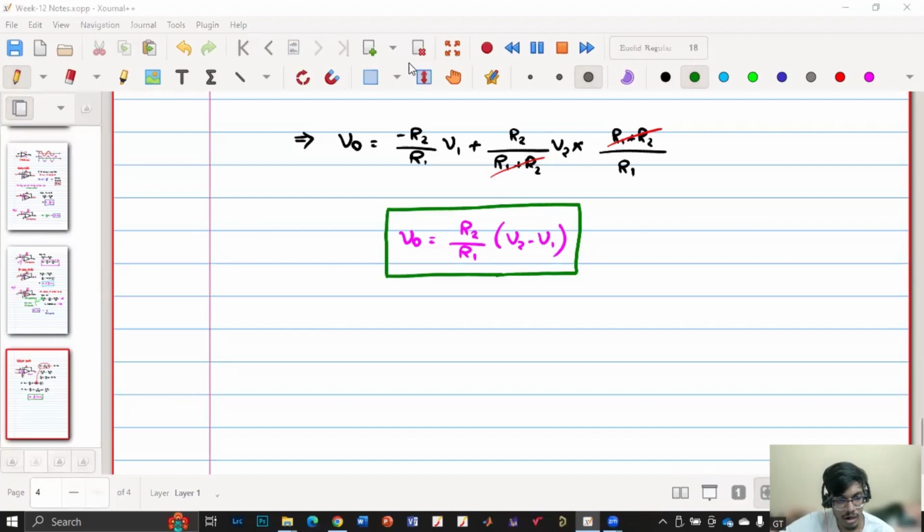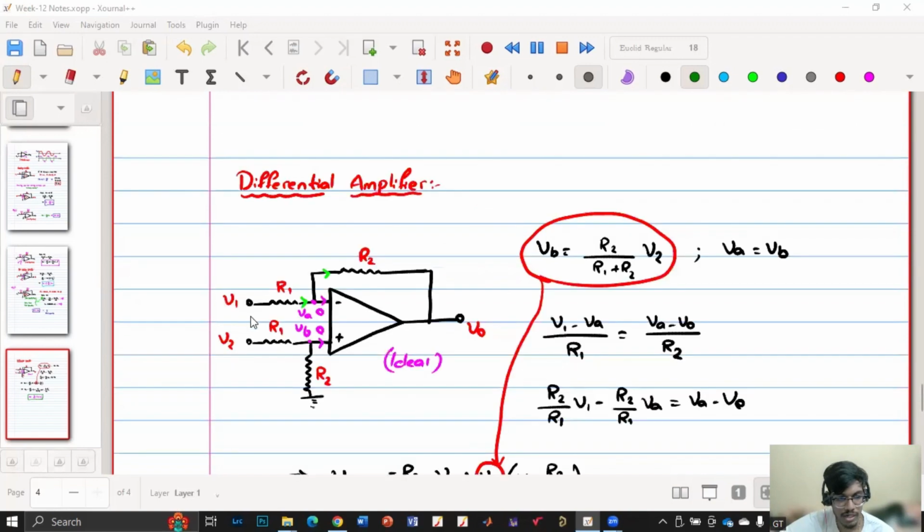So 101 ohm, yeah, that can also be considered, but usually this resistor should be a little bit high, else there will be a loading effect. So this resistor should be like in the data sheet they'll give. It would be better if they're at least in kilo ohms, so at least 1K. Below that, it is not recommended to use. It will be mentioned in the data sheet again. They will say minimum you have to use around 1K. In some cases, it could be lesser also, but whatever I'm using, it is at least 1K.